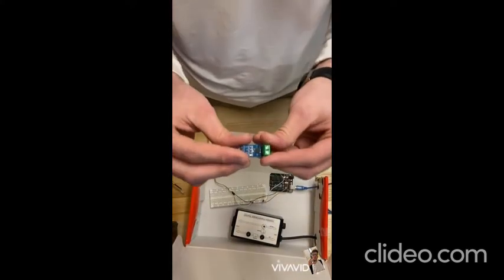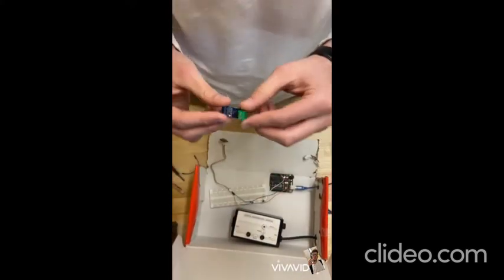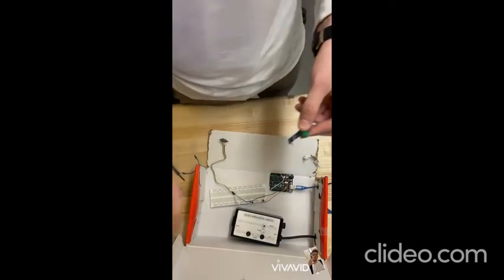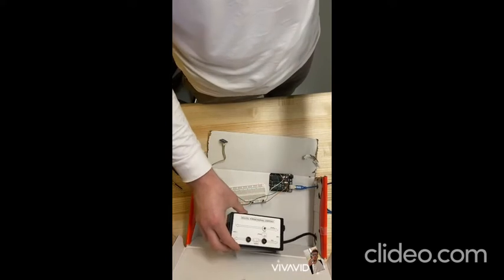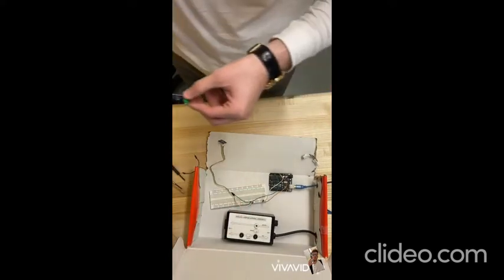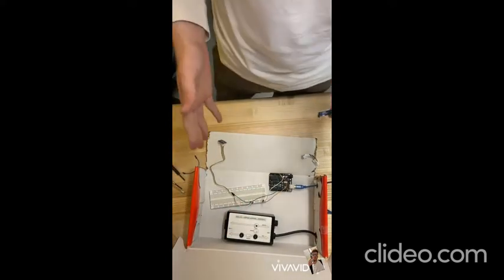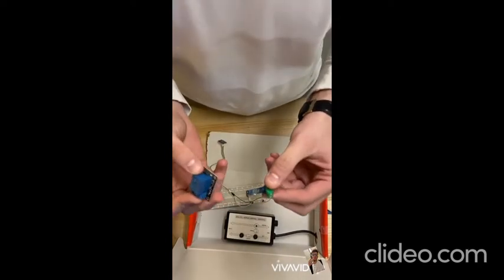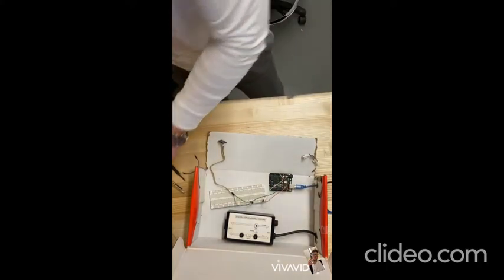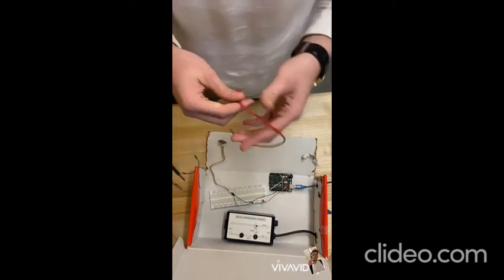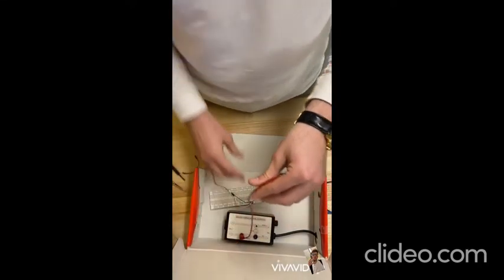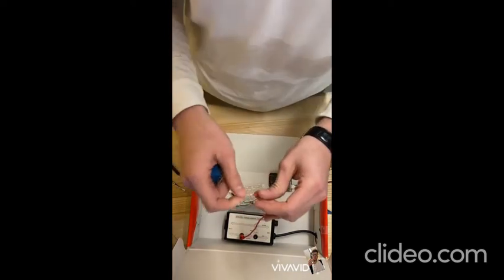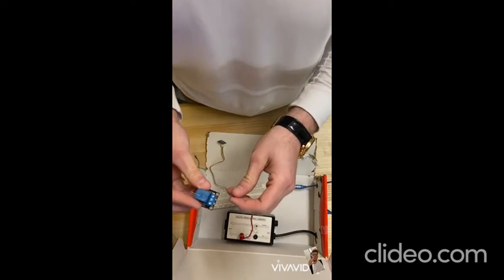So we've got our current sensor, and instead of cutting the wire of the heater itself, I got this transformer tester so that I can extract the current from the heater and make it go through the current sensor and the relay without causing any damage to the heater itself. So first we plug this wire in here, and then we plug this side of the wire into the relay.